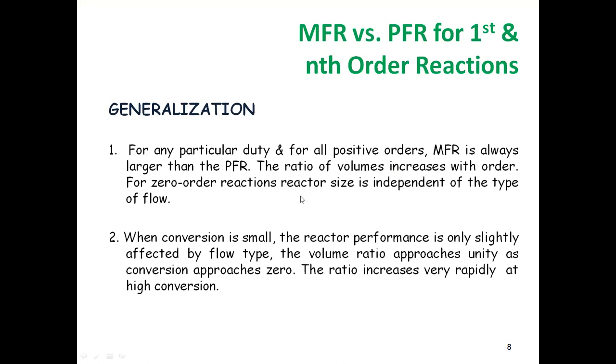For zero order reaction, take note of this. This is very important. Reactor size is independent of the type of flow. So if n is equal to 0, the reactor size is already independent of the type of flow. So whether you have facilitated it in a mixed flow reactor or in a plug flow reactor, for zero order reaction, it doesn't matter anymore. When conversion is small, so when XA is small, the reactor performance is only slightly affected